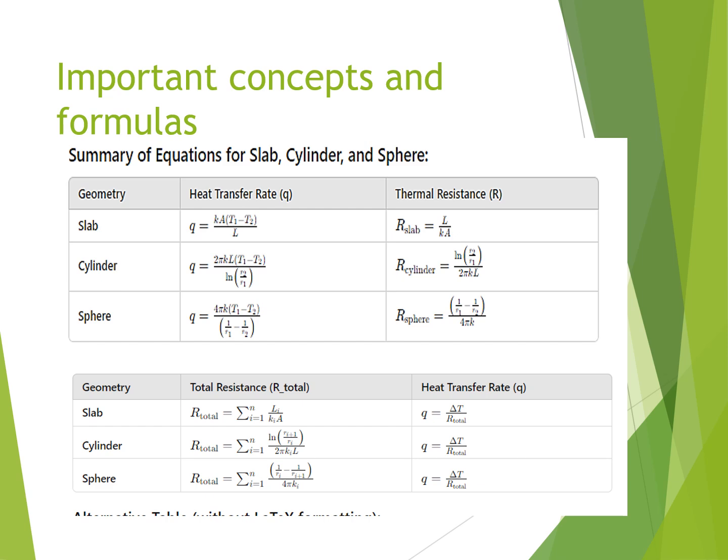Okay, that usually numerical problem come in GATE, and the formula that are very important is like already I have discussed conduction, right? So conduction through a slab is already being given. Geometry wise, conduction differs, the resistance, the flow differs. In case of sphere it is radially happening, in case of cylinders it's the logarithmic mean of your total surface area, in case of slab it's just the thickness difference.